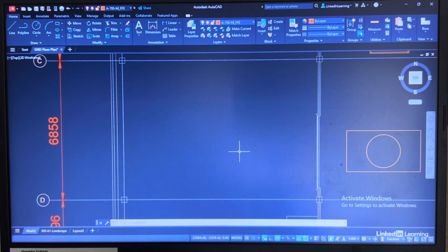Now we're going to create the same size table, but just use the line command this time. In fact, we could use the polyline command. It doesn't matter. Either one will give the same result. The only difference is when you close the polyline, it will be a closed whole object like this one here. Can you see that's a polyline? If I drew that with 4 lines, it would be 4 lines sharing common vertices.